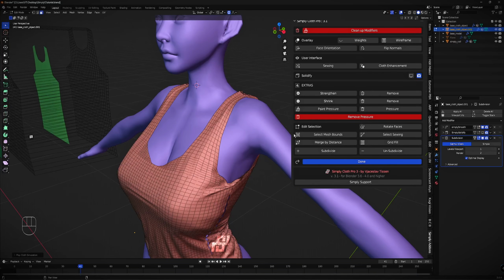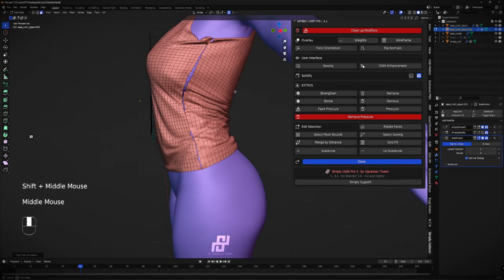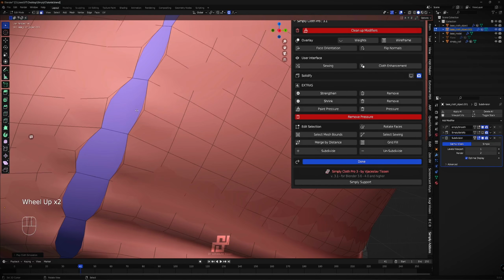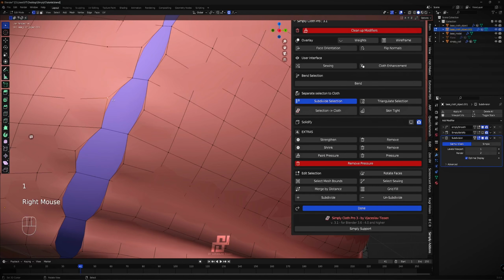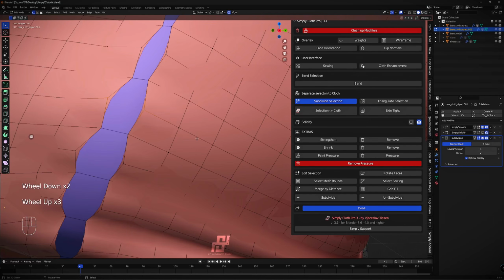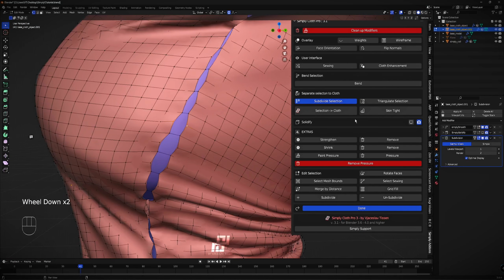And that's it. You go automatically to edit mode to close the sewing holes. These are these parts. And because of the subdivision we did before, without redoing the sewings, we have these gaps here. These are with no edges. What you can do now is we turn off the extras first.